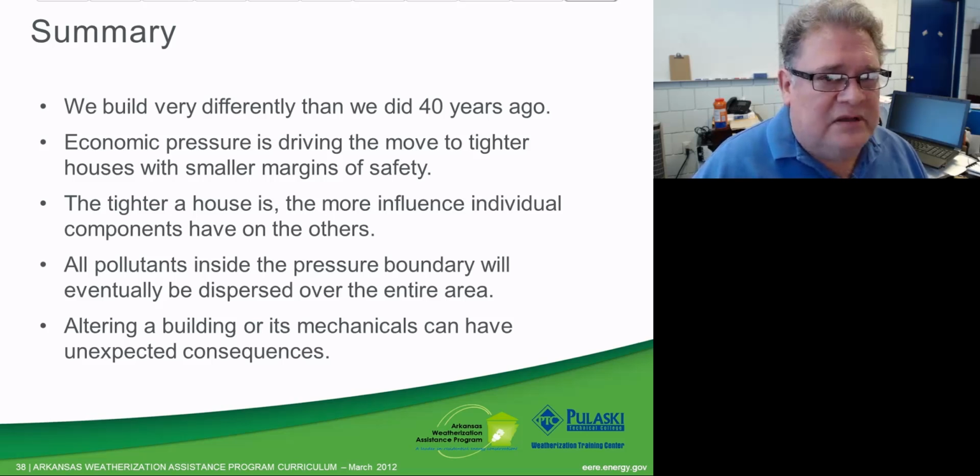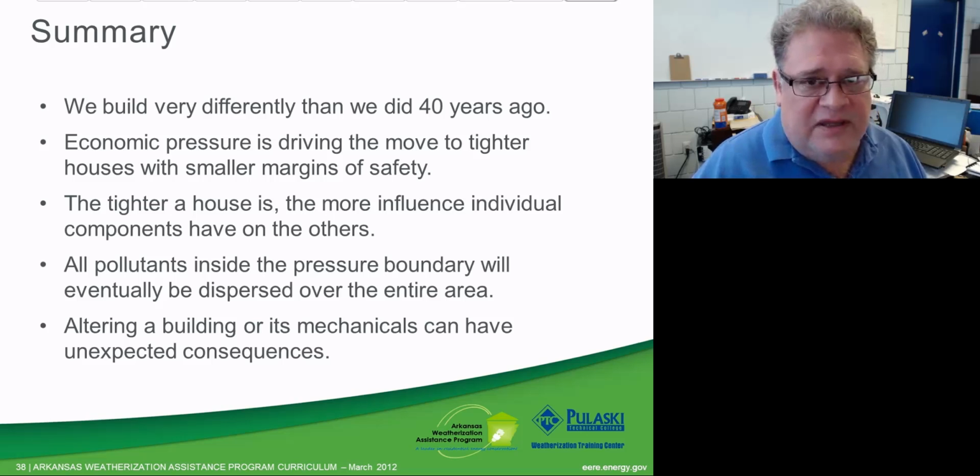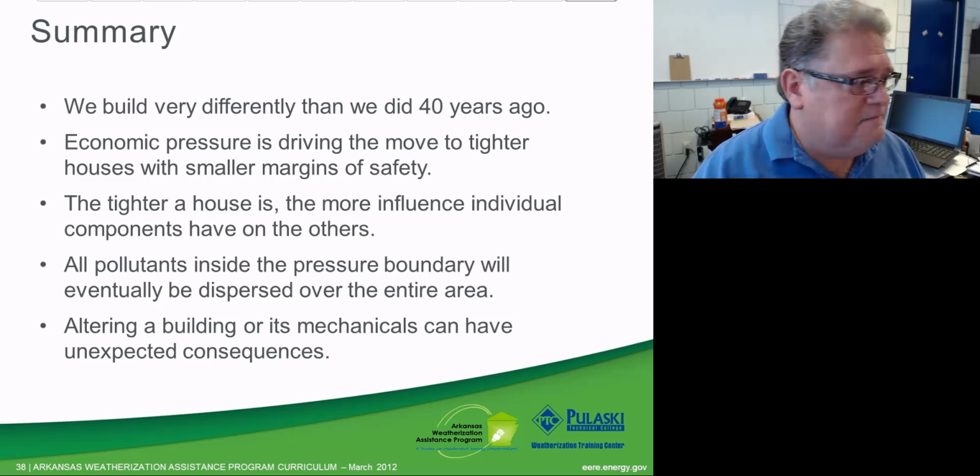If we mess with a building or its mechanicals, then we need to expect that something's going to change. We need to test in, baseline what the house is doing, how it's operating today, and then as we change things, we need to test out. We need to make sure that we're testing every time we make a change to that house before we go home to be sure we're not leaving a dangerous situation for the client.